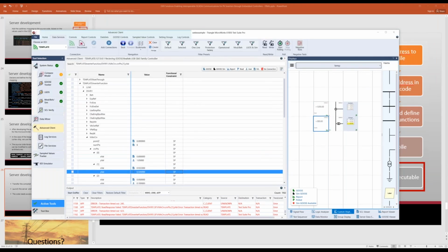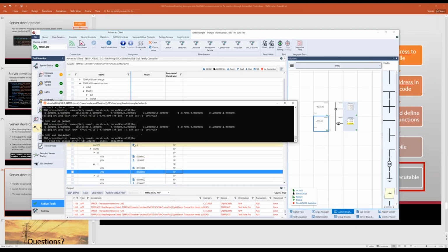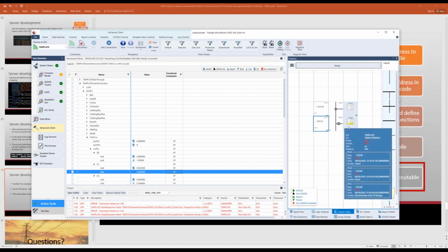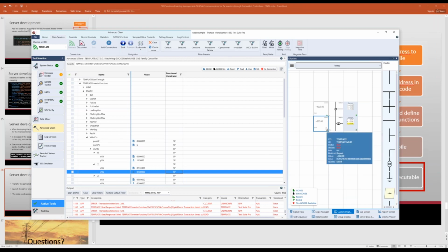But overall, you can also do other things with what we have in here. I'm also going to show an example of what is running in here. So you can see my volt-var curve basically updates with whatever value I give it. Initially with 0.1, and you can see what happens to the bar. All of that gets updated on the server side, and that gets sent back to the reporting. So the reporting basically tells you what is the latest value when there is a change, and it also tells you if everything is within bounds, and it is also timestamped. So you can use that in your application as well.